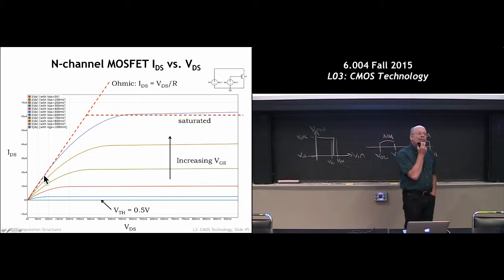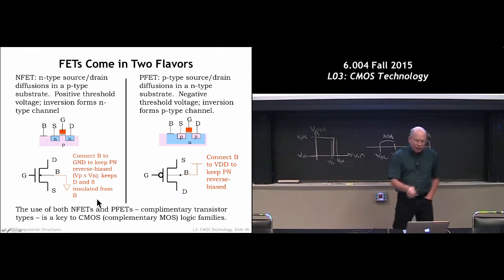Okay, that's more than you probably wanted to know about MOSFETs. It's more than you need to know for most purposes in this course. The real key that we want you to know is that when VGS is small for an N-channel MOSFET, the switch is off. When we put that voltage high enough, the switch turns on. So we have a voltage-controlled switch. Now we're going to talk about how to use those voltage-controlled switches to build logic.